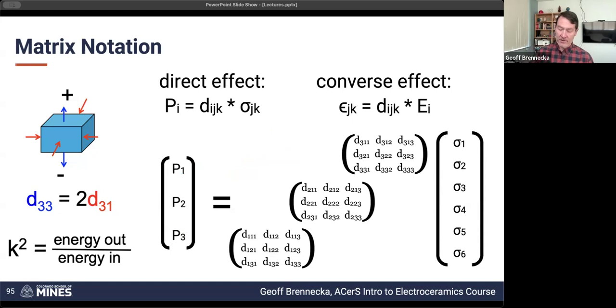The same sort of thing with stress, except now because stress is symmetric, as we can see on this end, when I strain something, I'm going to get a response in the alternate directions as well. So that means that I actually need 6 of them. And that ends up being, these are the direct components, and these 3 are shear.